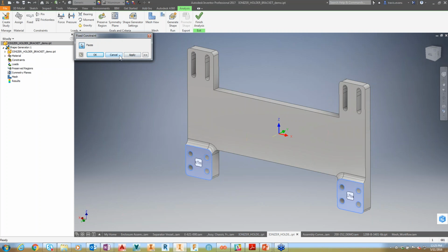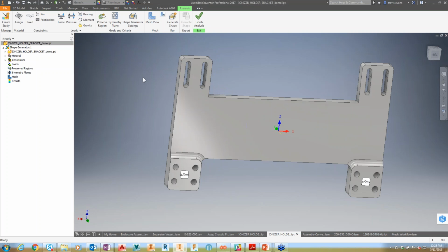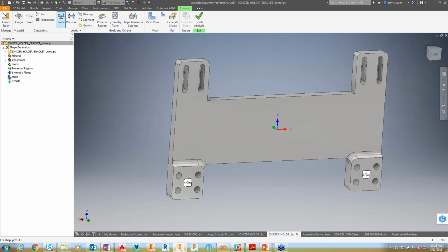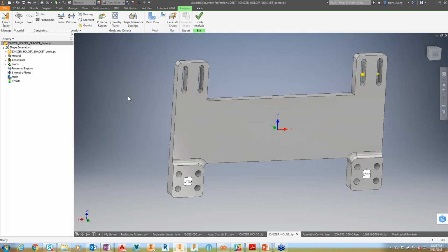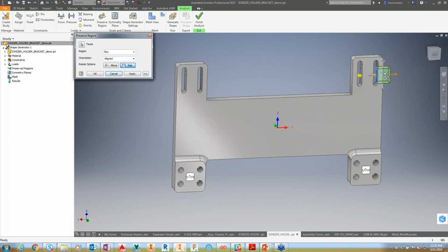And then I need to say what kind of force is being applied. Well, maybe the force here, because that top rail goes side to side, I'm applying 100 newtons of force. Okay, so I've got the entry level information that I need, and now I'm just setting up the specifics. The specifics here are what areas are of concern for me that I do want to maintain. So here, using a nice little bounding box and triad, I can start to manipulate this, and I can see, hey, I want to capture just those initial mounting points, so we can apply that.